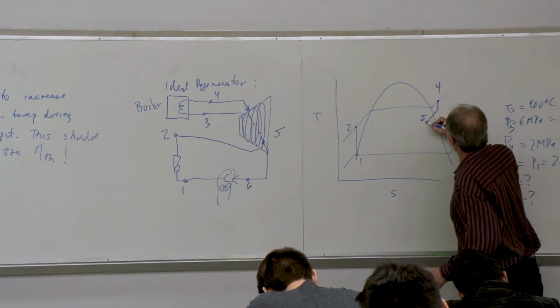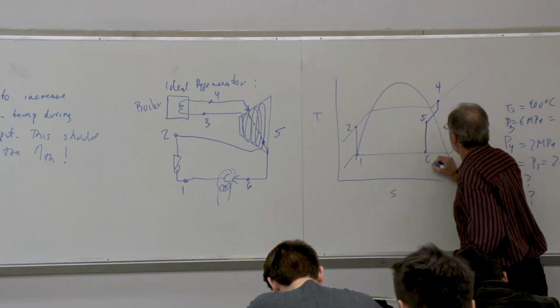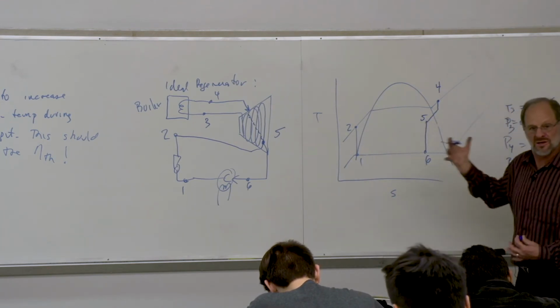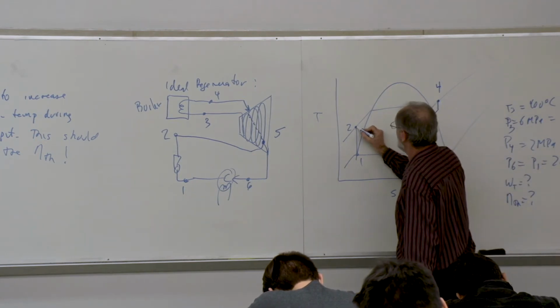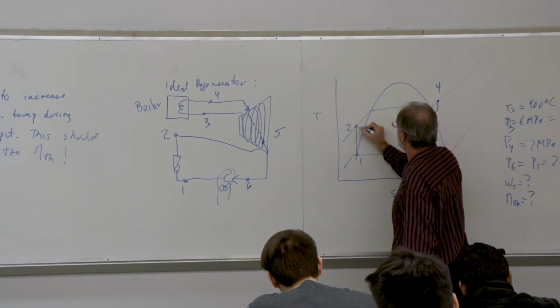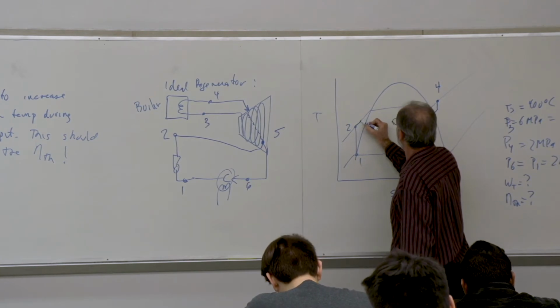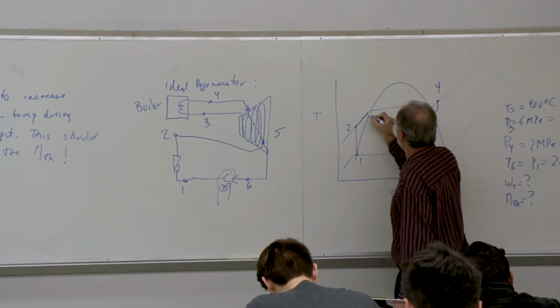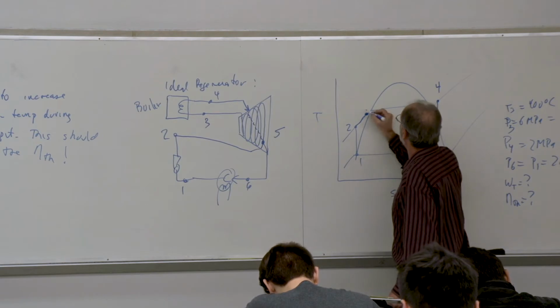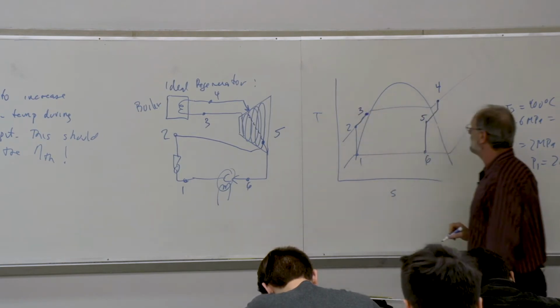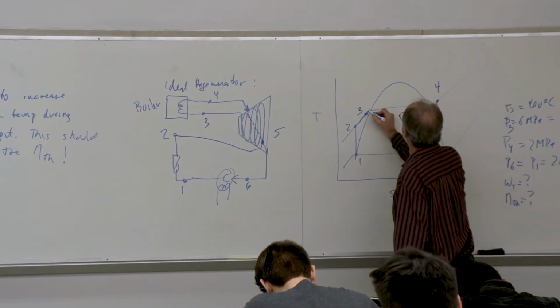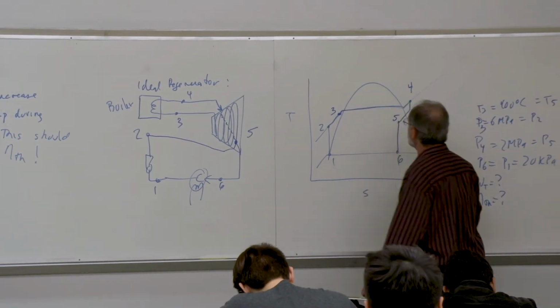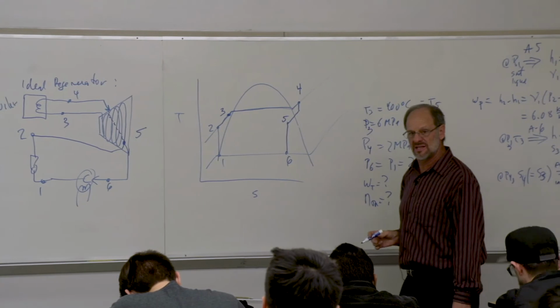And now the steam is just going to continue its isentropic expansion until we get to point 6. On the water side, as we leave the pump here at point 2, we're going to start picking up heat. So we're going to rise like this until eventually we get up to some higher temperature at point 3. Okay. And then we're just going to continue with the heat input process from the boiler, and that's what our cycle would look like, something like that.